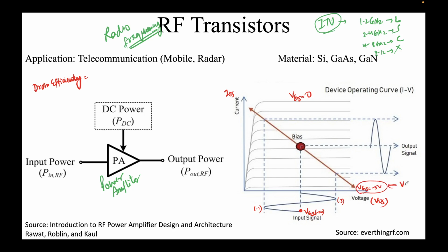This is the threshold VTH. Right, so we are swinging between -1 and -3. The input voltage is swinging between -1 and -3. Correspondingly, the IDS will take this plot. I'll mark this as I high, and this point I'll mark as I low. Again, this is the output signal. The output signal swings something like this, corresponding to the input signal. This is the IDS output signal.